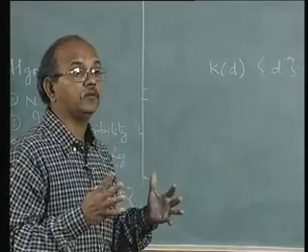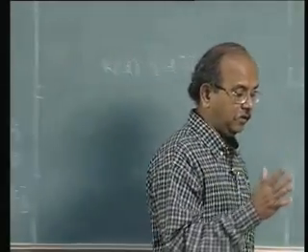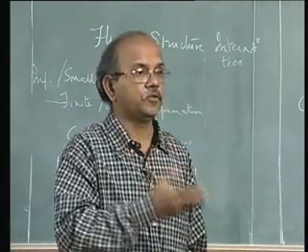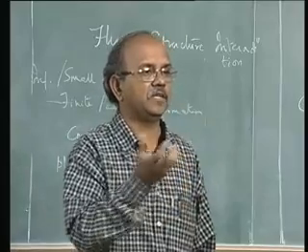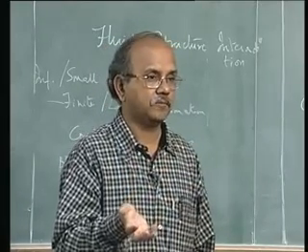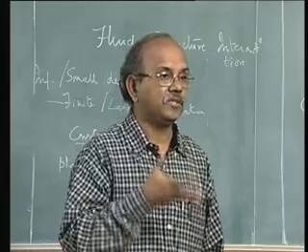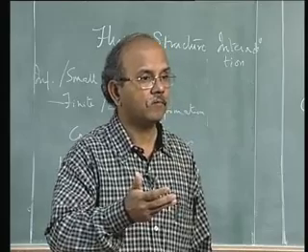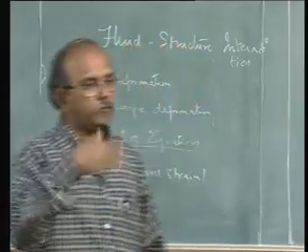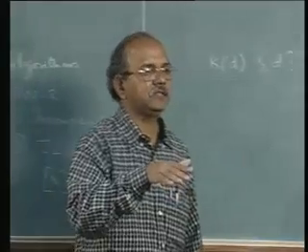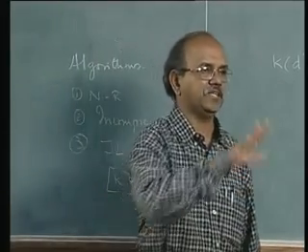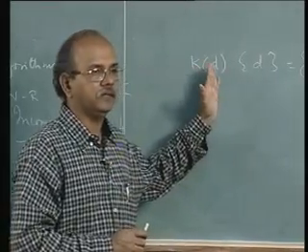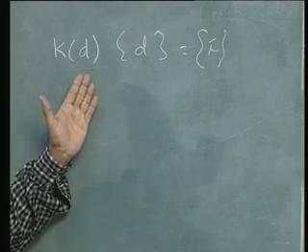The question that you may ask is, is it only a function of deformation alone? It may also be a function of damage. Suppose you are looking at damage mechanics, say for example, you are analyzing concrete or composites, and then there is damage in the material. Then k definitely would vary. You can of course say that damage is due to deformation, and so in one sense k is a function of deformation. So that is why I said that k can be a function of d or another parameter which is again a function of d, and so on.